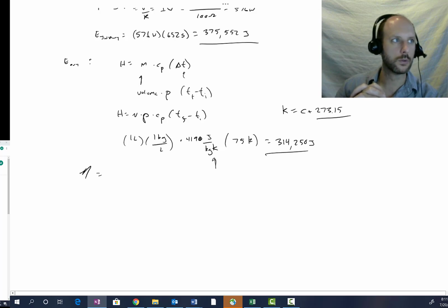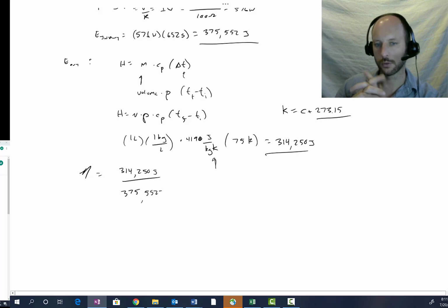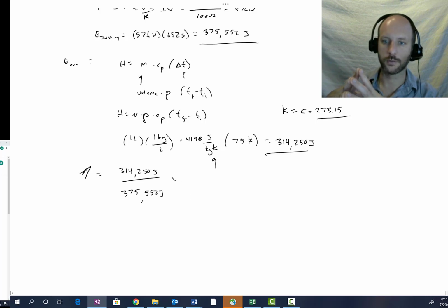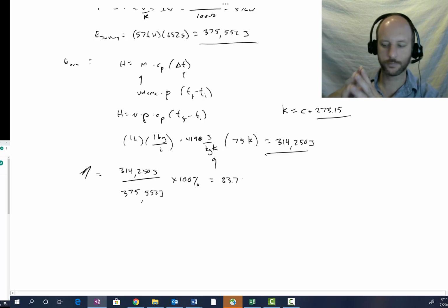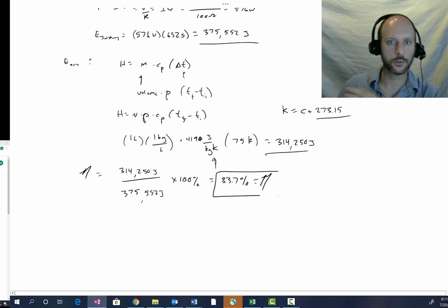Anyway, I do that math, I get 314,250 joules. So now it's just a simple matter of throwing those two calculations into my formula for efficiency. So the output into the water was 314,250 joules. We already determined that the electric circuit used 375,552 joules. I need to multiply that by 100% to convert from a decimal to a percentage, and we're going to get a value of 83.7% for our final system efficiency.